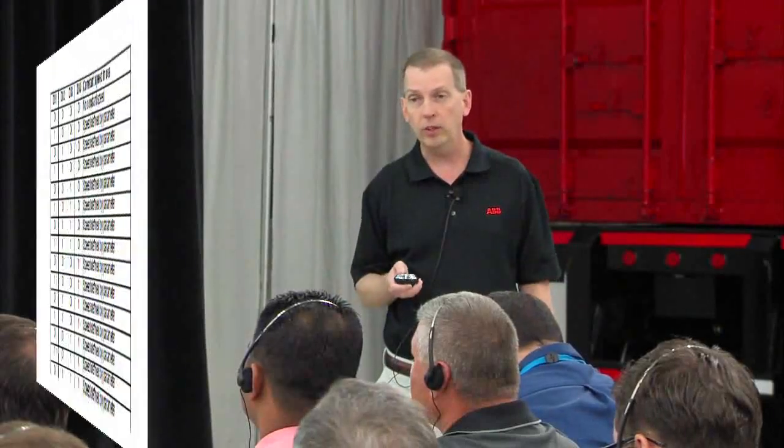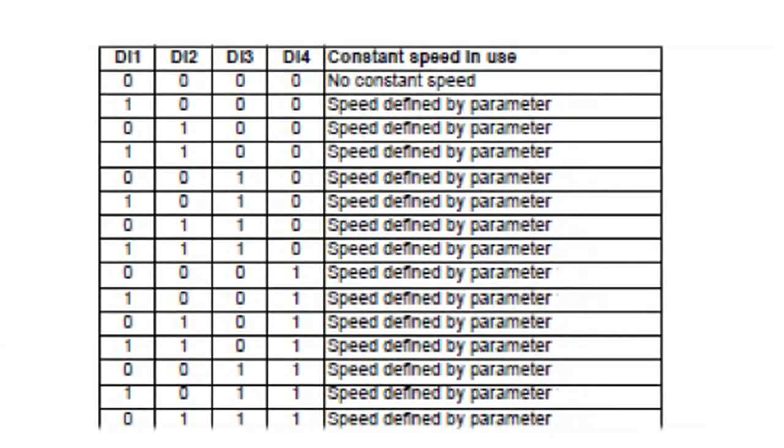So if you have an application where you really just need to go to very preset levels and you always want to go to those levels, a couple digital inputs will do that for you. Now, there's a couple types of controls. Drives are commonly used to replace motor starters.